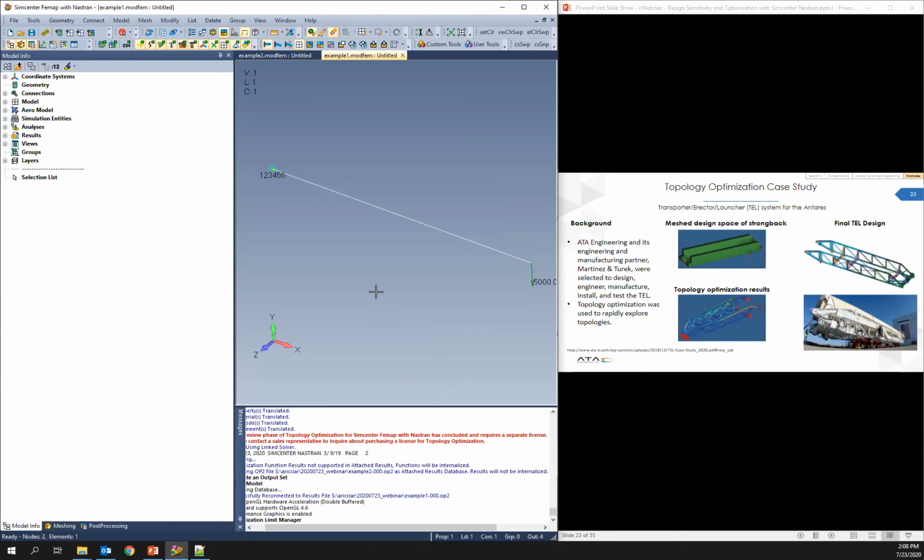So in Femap, it shows it as weight, but for a model where weight's really not defined, like none of the models I actually showed here, I defined the weight mass parameter, and so in that case, it's mass. So you do kind of have to look at the output from Femap if you want to confirm things like that, because in the Femap interface, they chose to label it as weight, and it could be weight in situations where you're using weight mass.